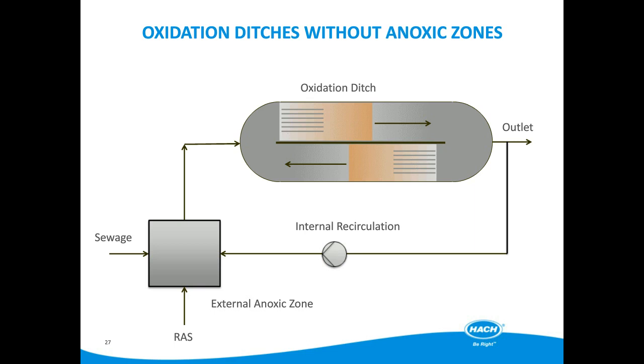They primarily go for compliance before energy saving, whereas with the measurement of redox within a ditch, although you are looking at the redox potentials, you don't have an idea of the actual ammonium or nitrate concentrations that are there, only what the potential is. So I would be guarded about using redox as the main control in that respect, because once the mixed liquors have exited the ditch and gone through the final settling tanks, then you've got no control of the system.